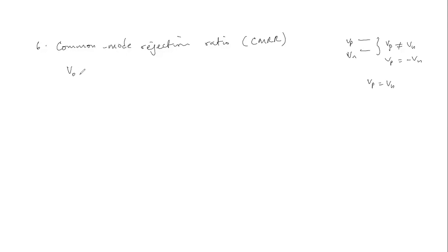And therefore we can designate this as V naught to be the same as A sub D V sub in, which is equal to, or better say plus, A sub C V sub C. And this is approximately the same as A sub D V sub D, which is the differential gain, which we'll be using as our convention most of the time. Okay, now